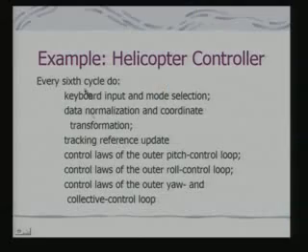at the same frequency, because control output can be generated at a slower rate, because I would like to look at the inputs over a number of sampling periods to decide upon a control action. So the control action may be generated every 6th cycle. Therefore the whole system becomes a multi-rate system, because you are sampling the inputs, you are checking for faults of the inputs at a particular rate, and you are generating control action at a different rate. This is a basic difference from the first system, which was doing the basic control action at the sampling period itself.